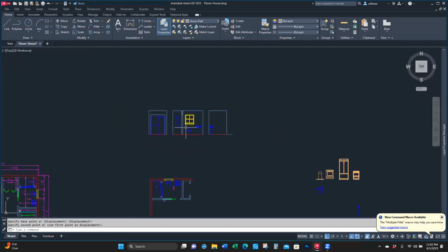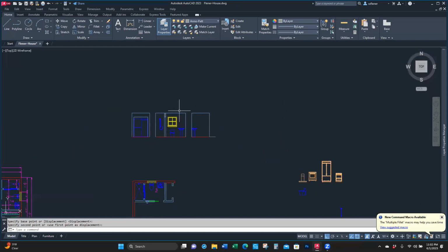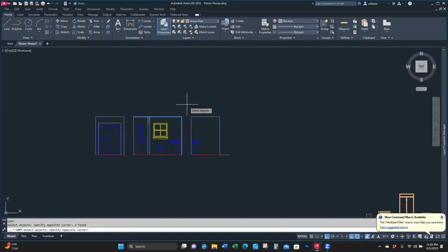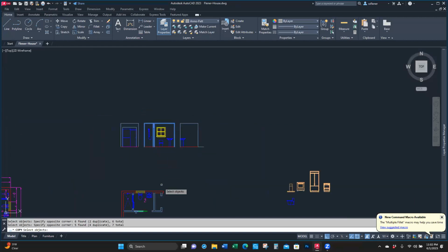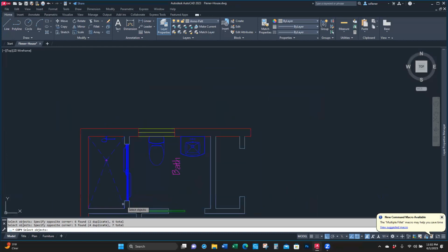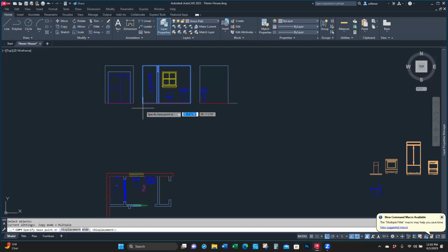And we can make a copy because we will see, and we'll do the outer lines, but we'll also see the spacing. So now I can move it, make a copy and move it, make a copy and move it by the left bottom corner to the end of that 24-inch line. And then hit enter and erase that 24-inch line because I'm done.